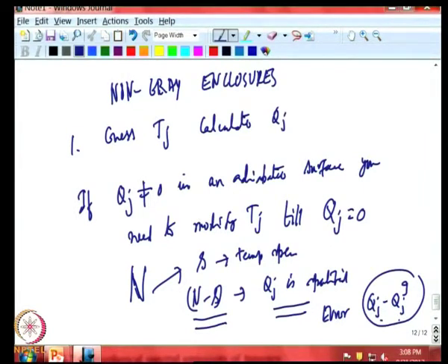But today with availability of very fast computers, it is possible to achieve that kind of convergence fairly rapidly, because it involves good initial guess. In all iteration techniques, you must remember that the initial guess is very important. You cannot assume arbitrary temperatures and expect your technique of iteration to converge to the right answer.